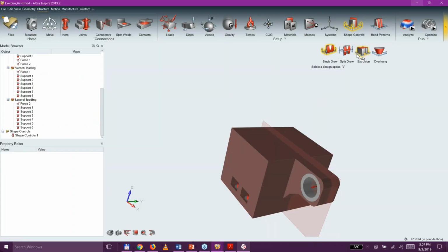Extrusion, the extrusion manufacturing process is to take some sort of semi-molten material and push it through a shape, and then we get a constant cross-section coming out the other side. What that guarantees is we have a continual cross-section running through the part.